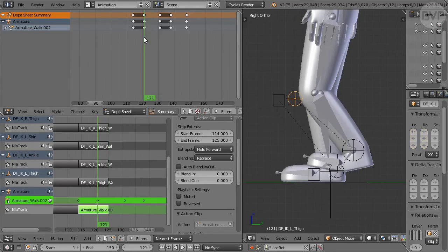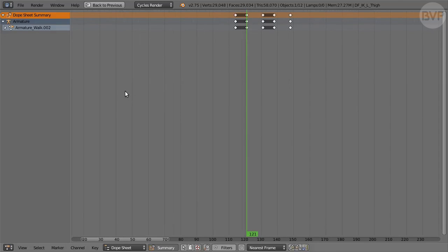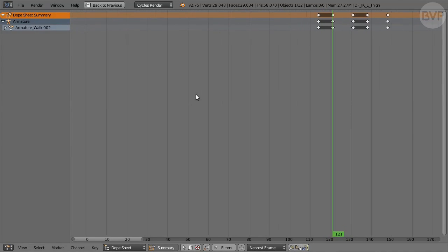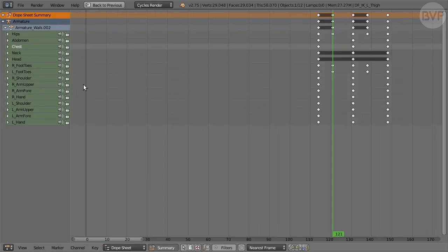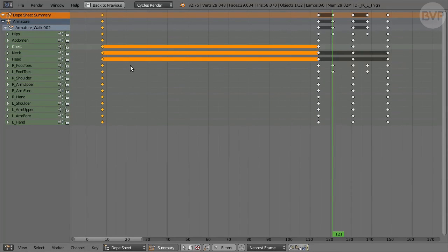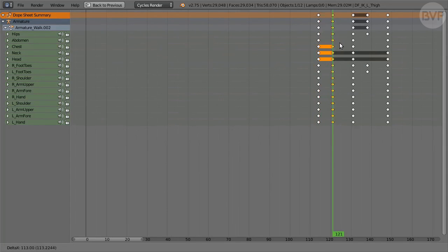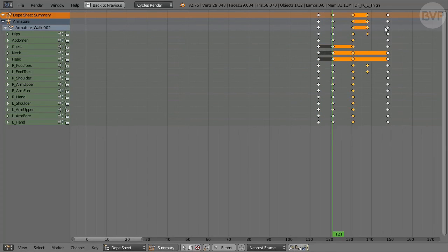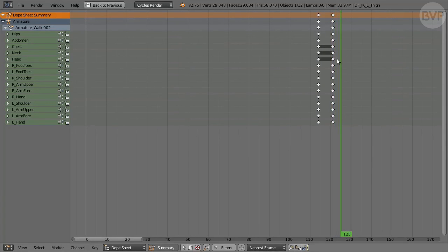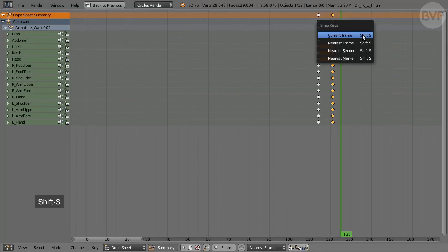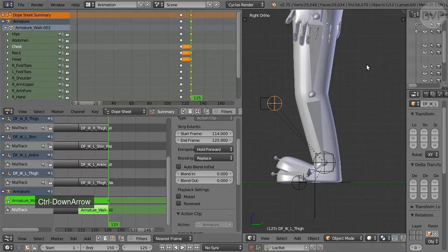Move the cursor to 2nd keyframe in Dope Sheet, enlarge the view with Ctrl up arrow and zoom the view to see all the way to frame 1. Disclose the bone channels, then press I and choose all channels. If keyframes are recorded earlier on, click their action diamond and drag them to the cursor position. Delete the 3rd, 4th and 5th keyframes. Then move the 2nd to frame 125. Reduce the Dope Sheet view.